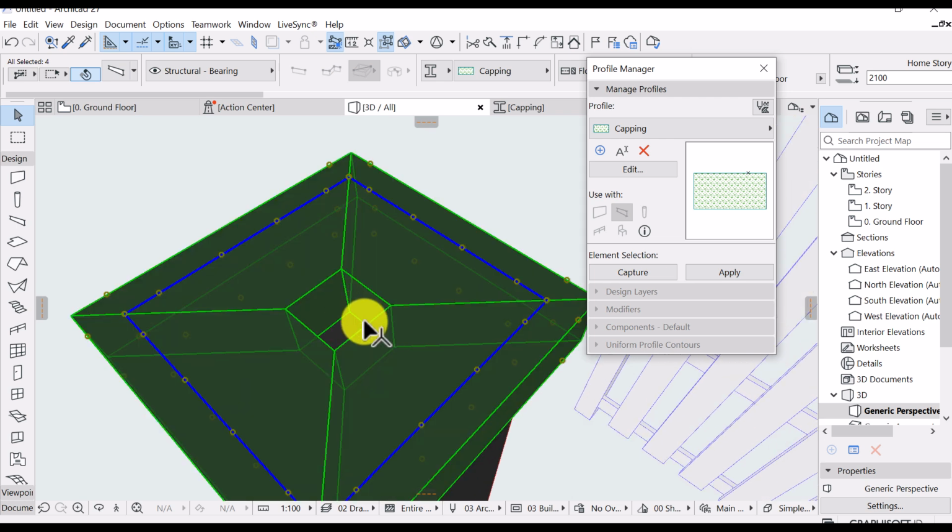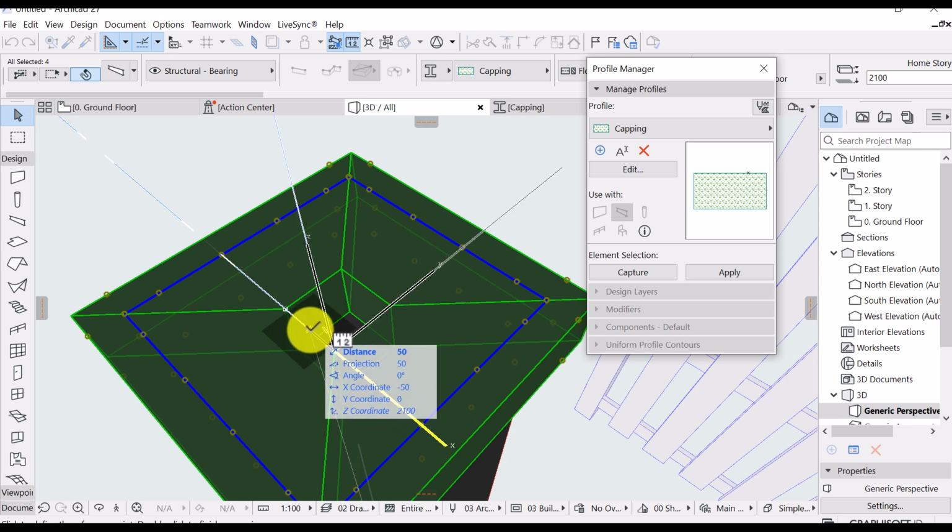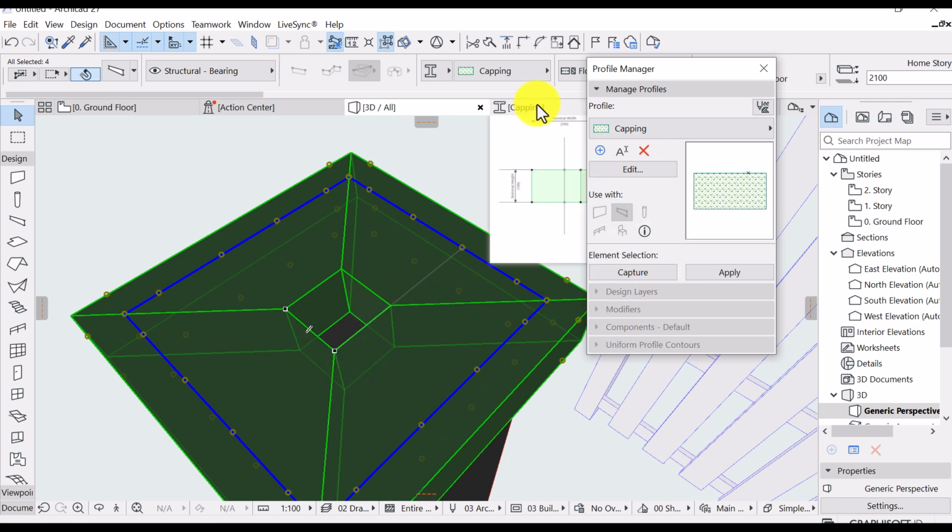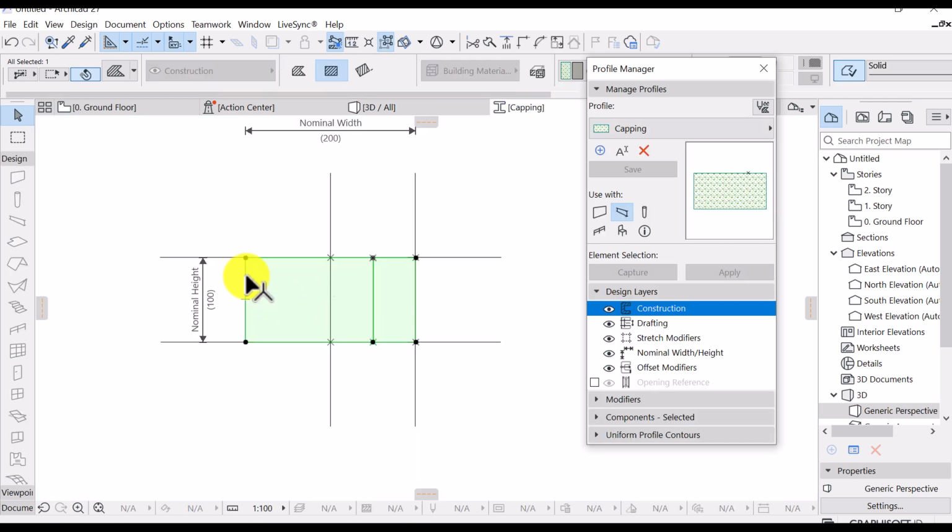I thought this would be closed. We have this little space that is left. I don't know why. I can just measure by hitting M on your keyboard. It was supposed to be 150 instead of 100, the offset that we did here. So I need to add that 50.